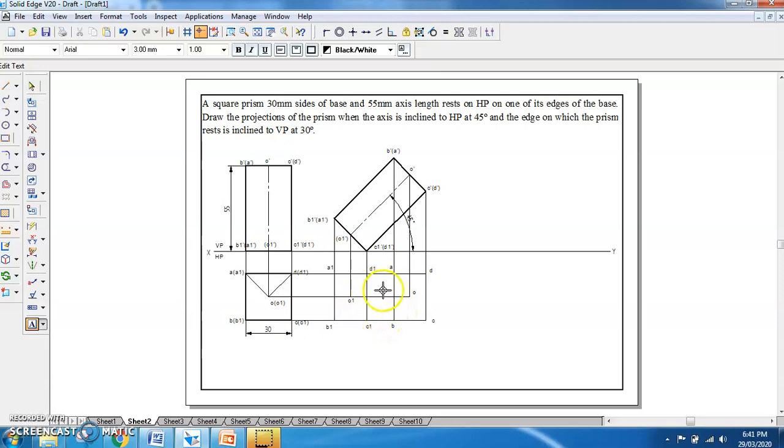So once you do all these things, now the observer is going to see the top view of this object from here. So when it sees from here, it will not be getting some of the edges visible. So first of all, you have to understand the procedure that you have the 8 corners of the solids here, and this O1 are the auxiliary corners which are there for the axis. So first you have to connect all the outer borders. So outer borders you have to connect by thick line.